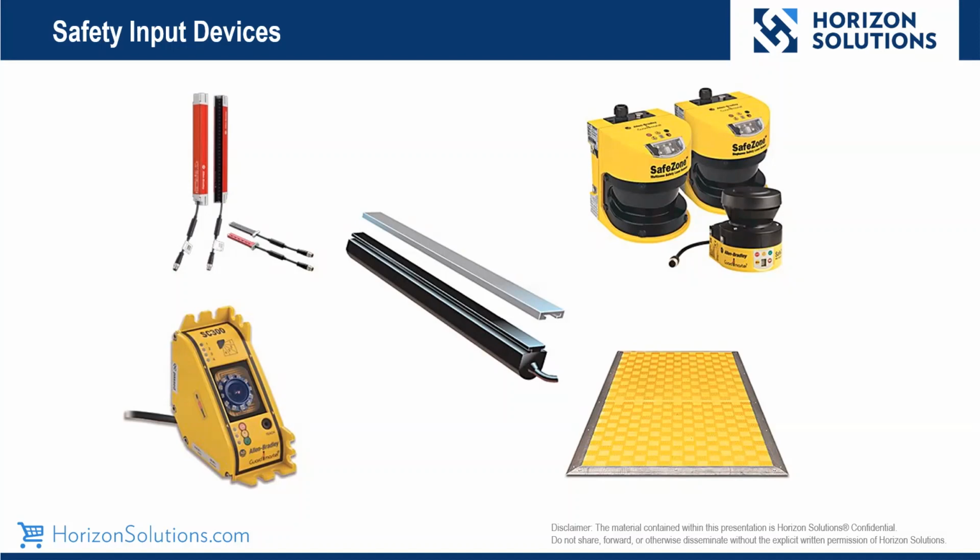This means that you can have the device closer to the actual hazard because we're going to be detecting the hand and the fingers before they approach the hazard, versus something like in the top right-hand corner, we have an area scanner, which is a very nice device and has its use cases. However, you are going to have to stop the machine faster while the person is farther away from the hazard because we cannot reliably detect exactly how close they are to that hazard.